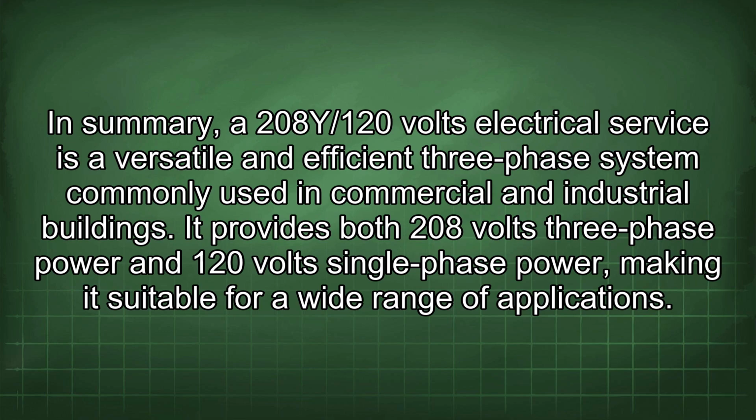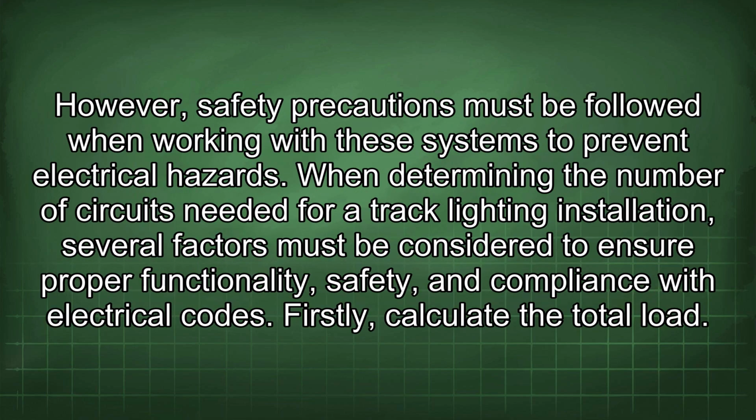In summary, a 208Y/120 volts electrical service is a versatile and efficient three-phase system commonly used in commercial and industrial buildings. It provides both 208 volts three-phase power and 120 volts single-phase power, making it suitable for a wide range of applications. However, safety precautions must be followed when working with these systems to prevent electrical hazards.